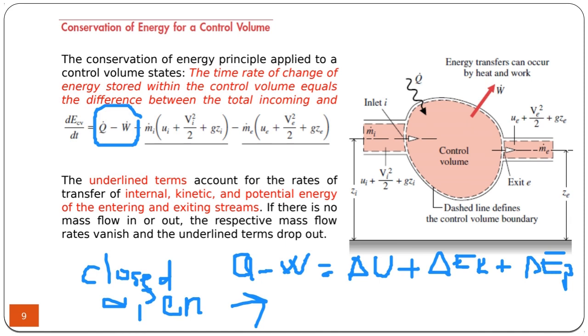If you are considering the time rate of change of the total energy content within the system, you can take the time derivative of the energy. So the total rate of change of the energy inside the system is equal to Q dot, which is the energy added or removed by heat per unit time, minus W dot, work added or removed per unit time. W dot is power, as you remember, and then we have the energy term due to the streams of fluid incoming and exiting.